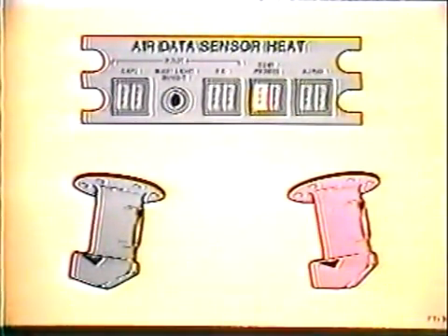There are two total air temperature probes. Each probe contains a single heating element. Each off legend represents a probe. Normally, the switch is latched and dark. When the anti-ice element fails in a temperature probe, the off legend will illuminate. The indication shown here is a heater failure for the left temperature probe.